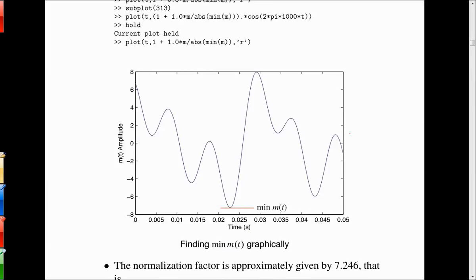You might be thinking, well, how does this really work in practice? Speech is a very random waveform. It's not deterministic. What really goes on in an audio processing system for AM radio is there's some sort of amplifier called a compressor amplifier that sits in front of the modulator and makes sure that the waveform stays normalized properly. If it's speech, they will compress it like crazy to make sure that it stays right at that normalization equivalent to the -1. And that's usually what you hear like in a sportscasting scenario.